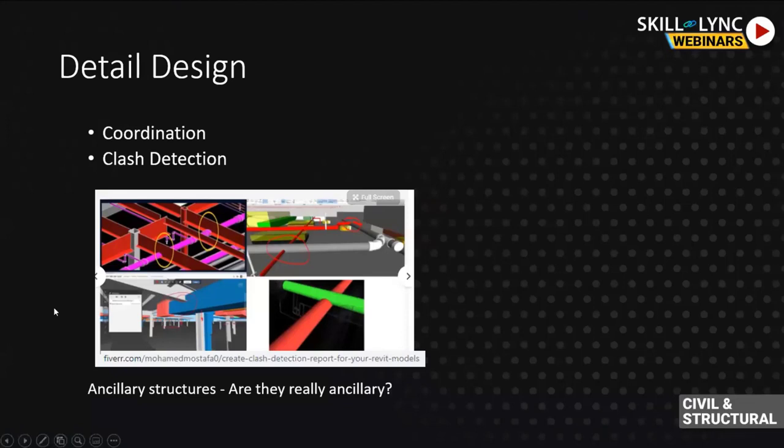Okay. And then there are ancillary structures. Although small structures here and there, but always think, are they really ancillary? So you have an existing masonry wall that you want to knock down. Be aware what kind of loads it is bearing. Are you ready for that? Do you have enough data to support whatever you are doing? Do keep asking the right kind of questions. They'll take you to places, because it is very easy to miss on these points.